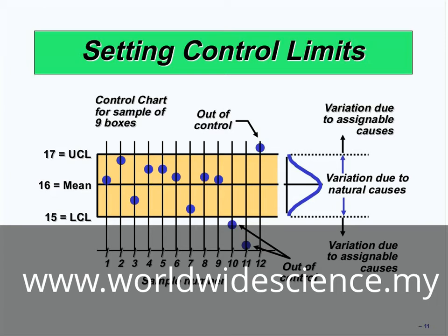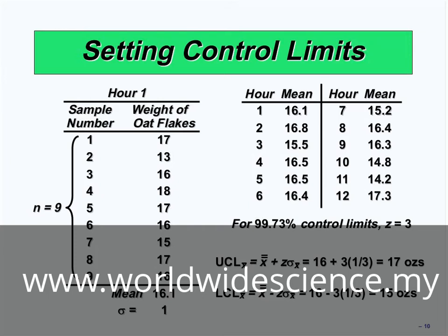But as you see, 3 spots have fallen out of this area. Number 10, number 11, number 12. Because in hour 10, the mean or X bar was 14.8.